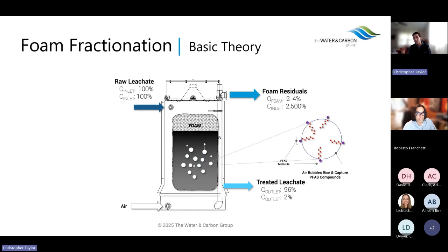So that kind of gives you the freedom to, let's say, add foam fractionation, or add fine bubble diffusers to the system, a bunch of microscopic bubbles. I'll be able to create foam very easily now because I don't have to deal with the higher surface tension of water. In fact, you create it so easily that it creates the perfect transport mechanism for PFAS to be lifted up and out of the system.